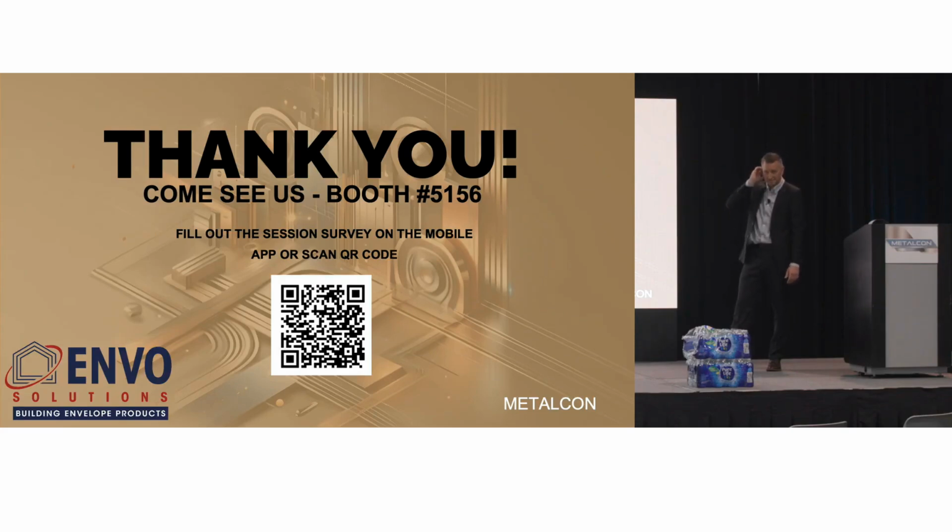Can you stand on the rigid boards, like on the roof when you're installing? Are they strong enough? Right. So of the 2 rigid boards that are common in the market right now, the Thermax board is not tested for a walkable surface, but the R-Seal is. So you can put down the R-Seal boards on the roof and then walk on them to install your standing seam roofs on top. So it is a benefit of that one system, but that's a specific product in the industry, not rigid board in general.